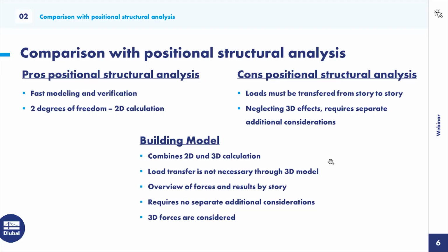As I said before, we have these 2D and 3D calculations and can check them on their own. And as I said, this load transfer is not necessary because we have one 3D model, and when we change something in the 3D model, all load transfer is automatically updated, and you can avoid so many mistakes with that.